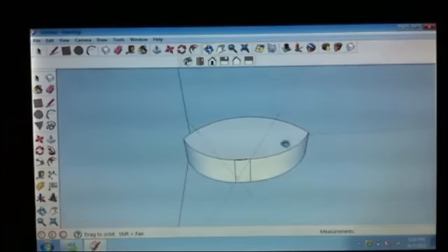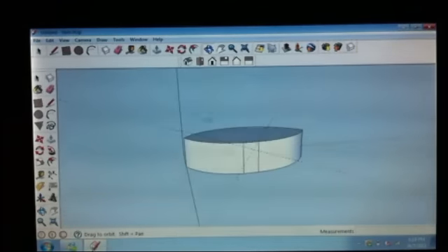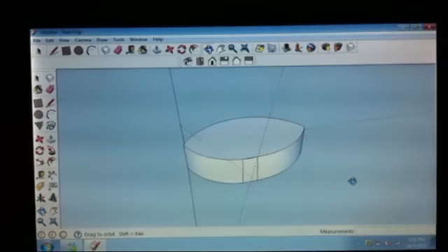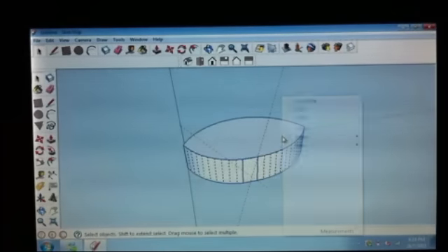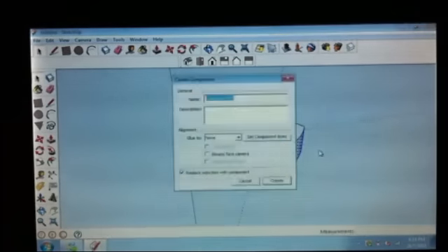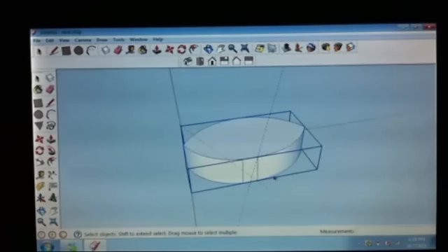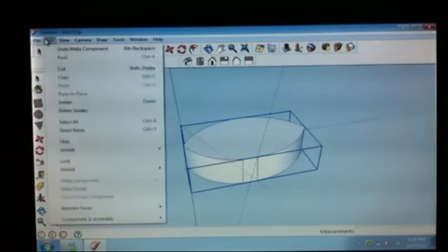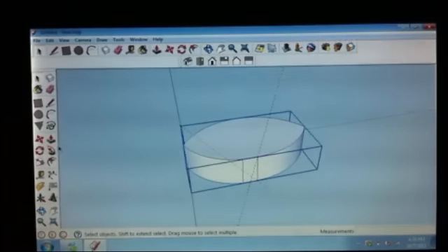Remember just now you have done all the base, everything done. So now you have to make sure that you lock this up as a component first. Make component, create. So this is actually positioned at the base. What do I mean by that? If I unhide it, you can see that the base will smash right into here. So I'm going to move this thing first.